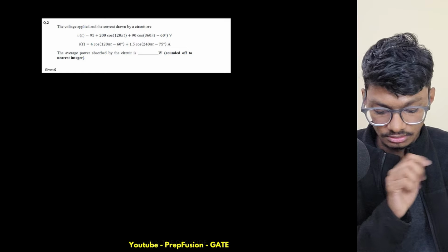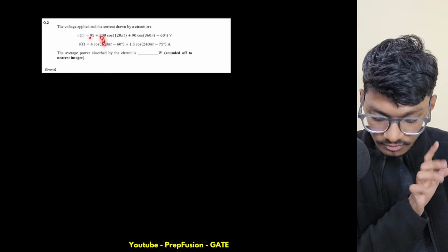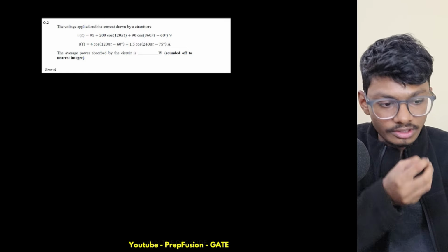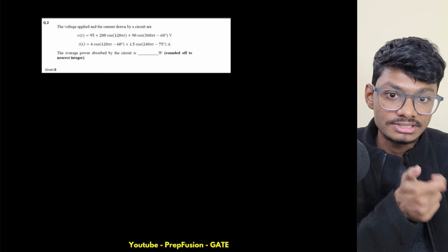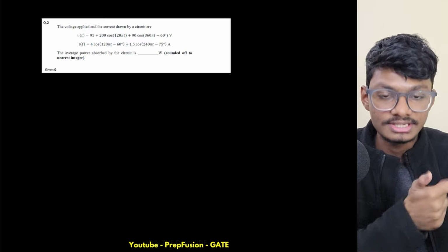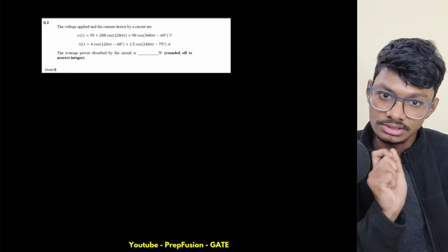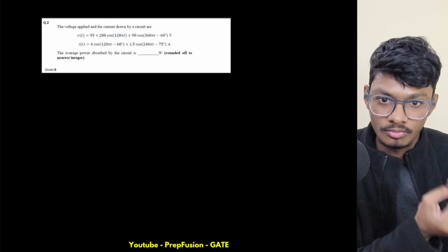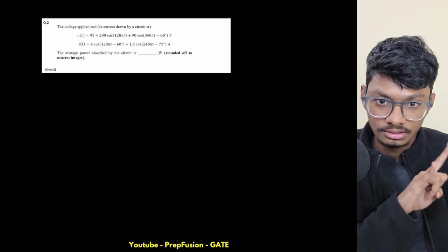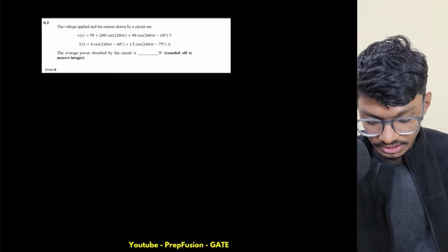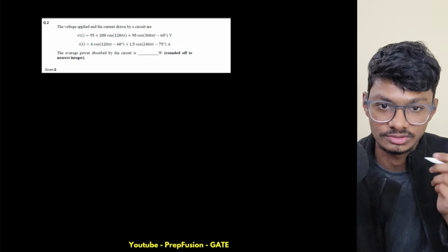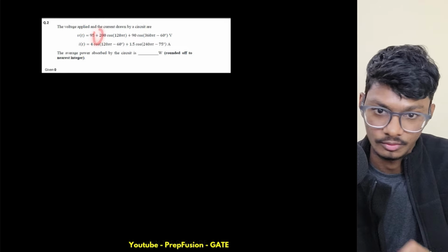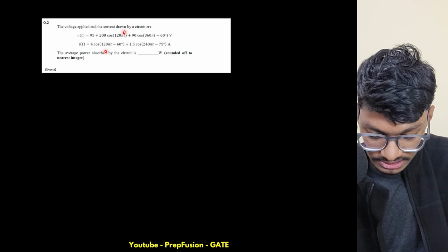Hence the voltage or current signals that are orthogonal will vanish. Only the signals which are not orthogonal, that is, the angle is not a multiple of 90 degrees, will contribute to some power, absorbed or delivered. Other signals won't contribute. Here this 95 has frequency zero, and everything else has some frequency component.